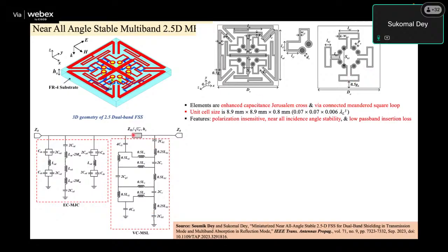In between, you have this. What is this? This is nothing but your dielectric layer, because the signal is going through the dielectric layer. This HS is the length of your transmission line, that you can see over here. Now, all these things are a function of the kind of inductor and capacitor you are considering in your structure. So this is the way you have to come to the equivalent circuit model.